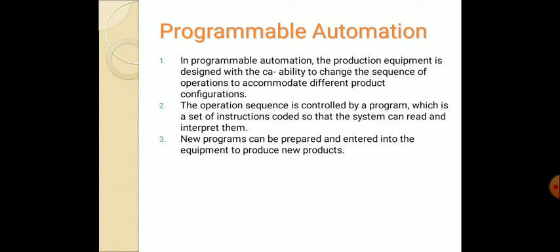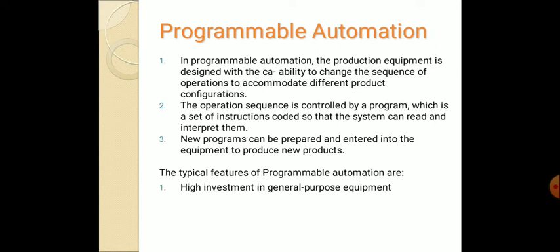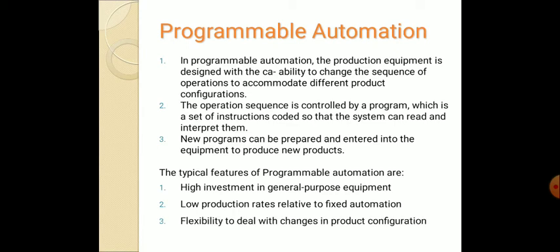Some of the features that characterize programmable automation include high investment in general purpose equipment, low production rate relative to fixed automation, then flexibility to deal with changes in a production configuration.